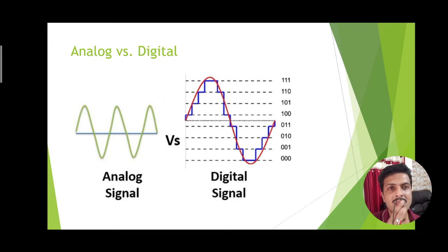So these steps are further required to be coded with binary 1 and 0, where 1 represents the high voltage and 0 represents the low voltage. This high doesn't mean very high, but it is around 5 volt, and 0 stands for 0 volt. Now there are other definitions of logic 1 and logic 0 depending on the system, where 1 may be represented not by 5 volt, but by a range between 2.5 to 5 volt. 0 may be represented by 0 volt to 0.8 volt. So it depends from system to system, but still 1 and 0 represent a very low voltage.